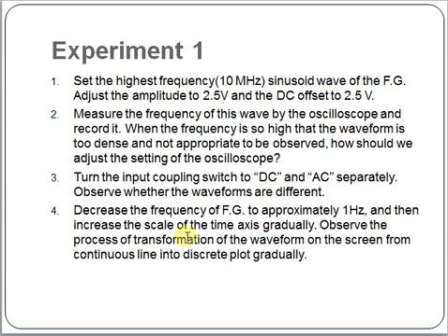Set the function generator to generate signal of approximately 1 Hz. Change the scale of time axis. You'll see the figure changes.